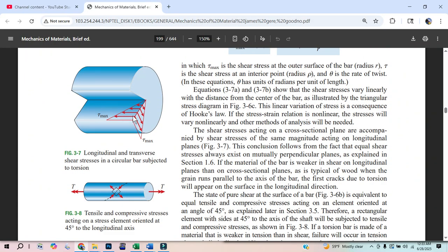So we're talking about this in form of twisting. We twisted it. That gave us what this T max was. Should we do that again? We twisted this rod visibly. I see an angle form. I'm going to take that angle divided by 360. That's a proportion of the circumference. That's going to give me how much circumference this thing rotated.